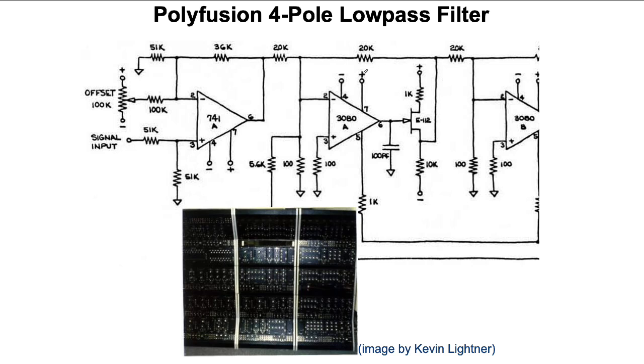Right now I want to focus on the feedback structure within a single pole itself. So here we have the OTA, and here we have a 100 ohm resistor. If you dealt with this as an ideal OTA, you would just say that this is ground. This 100 ohm here is probably to deal with non-ideal input currents. So we have this 20K resistor here, and we have 100 ohms here. So let's see, that's 100 divided by 20000. So if these cancel here, I'm using the approximation of R big plus R small equals R big. Let's see, so at this point, going into the OTA, we're dividing the voltage down by a factor of 200. So quite a lot.